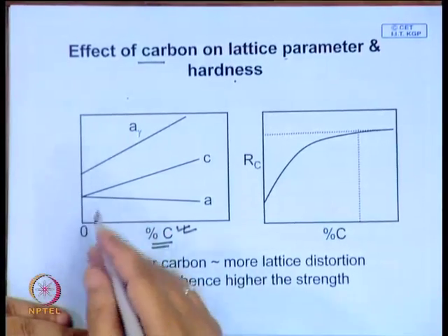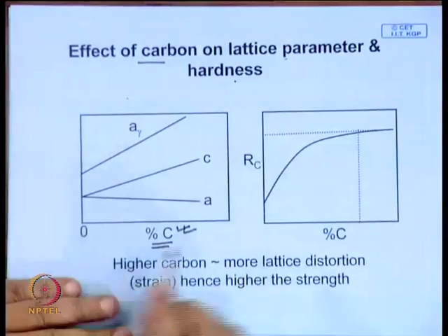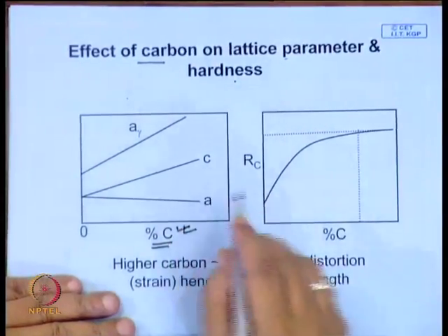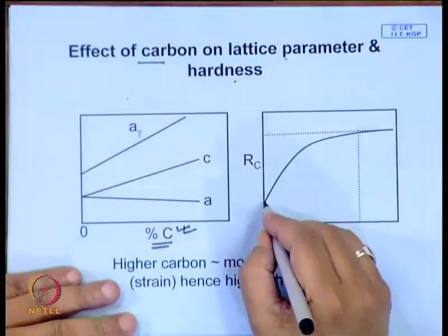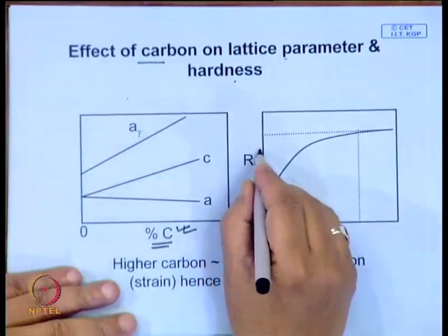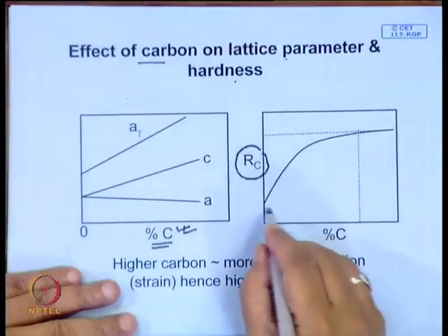The distance may be several atomic layers, say 8 to 10 atomic layers. So, it is actually a nanostructure. Now, this fine structure can be seen only under electron microscope, and such fine structure definitely is associated with increased hardness, which is reflected over here.